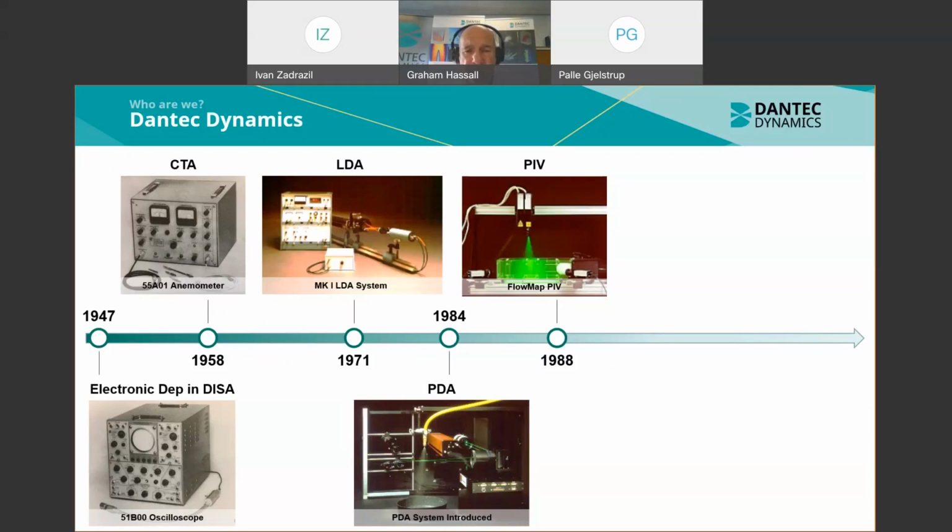This led to the development of particle image velocimetry, or PIV, in the mid-1980s, where images were recorded on wet film, processed and then analyzed to give particle displacements over an area. This required great patience and introduced severe limitations with respect to observing how a flow develops over time. The explosion of usage of the technique really started in the late 1980s with the advent of CCD cameras, which gave the possibility to observe the time history of the flow over significant fields of view, which when combined with dual cavity lasers gave researchers a tool to use in the lab.